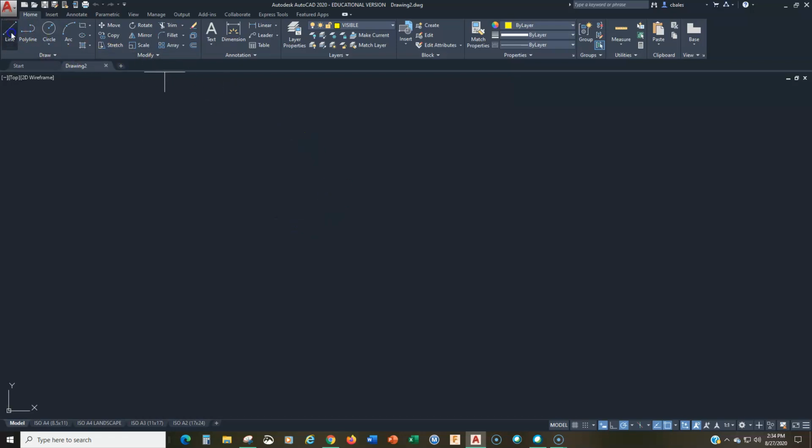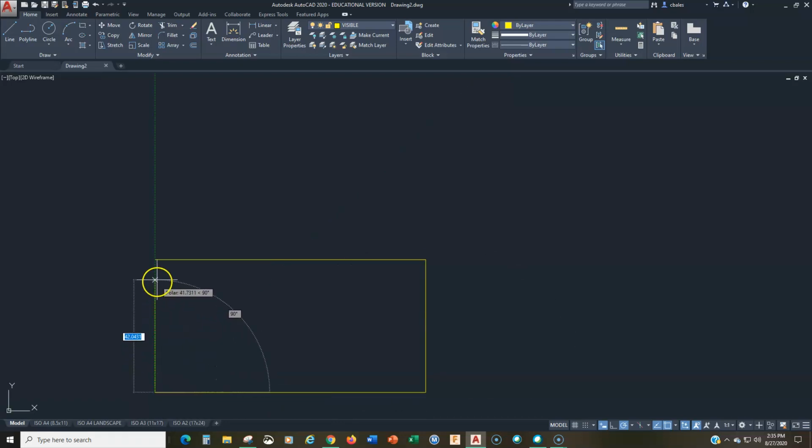So I'm going to go ahead and get the front view in there. So this is 100 millimeters. Whoops, 100 millimeters. Let's see, this is 50 millimeters. And we'll go down here 100. Notice how I'm using the object snap tracking to help me with those lines, the horizontal and vertical lines, to make sure that I'm drawing things accurately, also known as direct distance entry with polar tracking. Whatever you want to call it, it just helps because I don't have to enter in the angle. I can just use the horizontal and vertical.